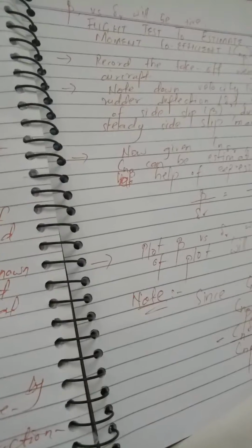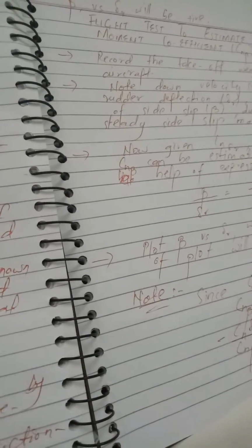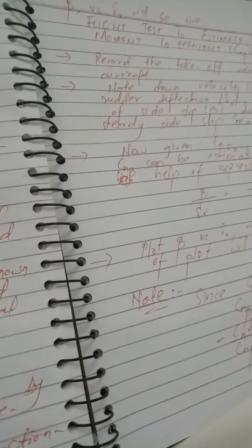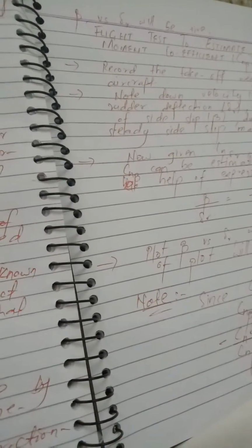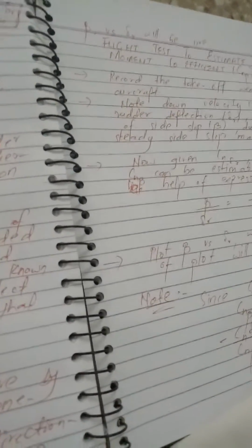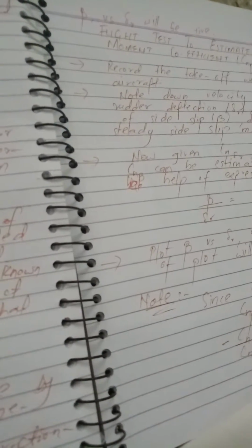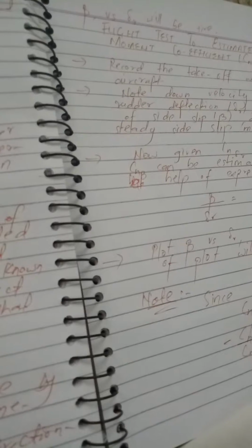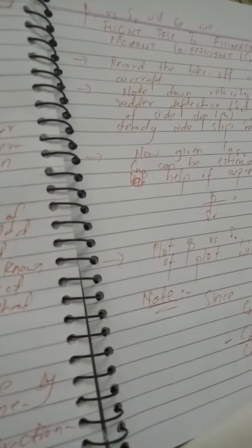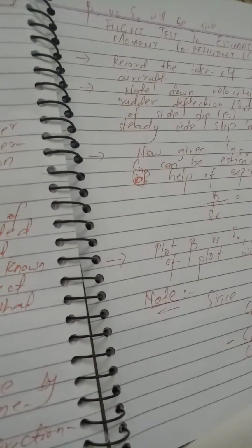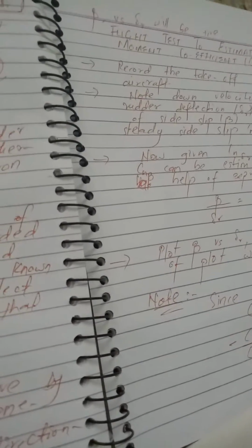But the dominating factors we are talking about here are in terms of lateral and directional stability, and in this case we have talked about the directional stability, and the side slip coefficient is being covered, which was by that equation which we have derived for Fy, and we have actually added the weight factor as well.